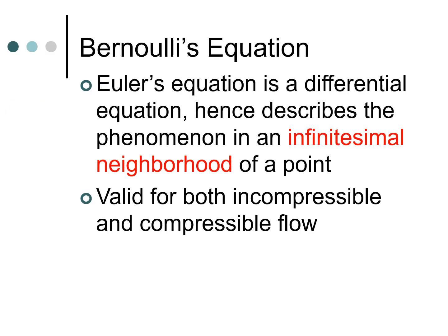Now the next equation we are going to look at in today's lecture is the Bernoulli's equation. We are going to look at it because it can be derived from the Euler equation, and it gives us a relationship between 2 points in the flow field. If we look at the Euler's equation, it's a differential equation, so it describes the phenomena in an infinitesimal neighborhood of a point. Again, we saw it's valid for both incompressible and compressible flow because we didn't make any approximation or assumption about